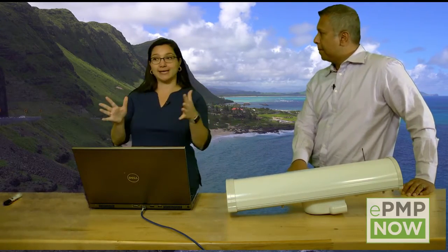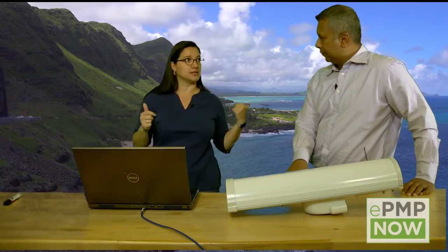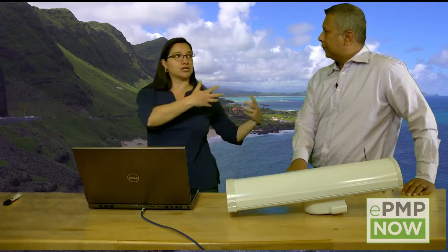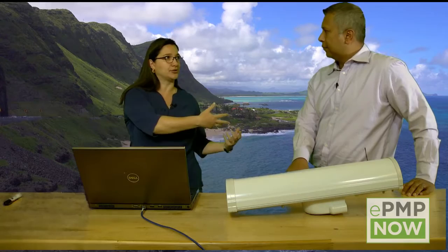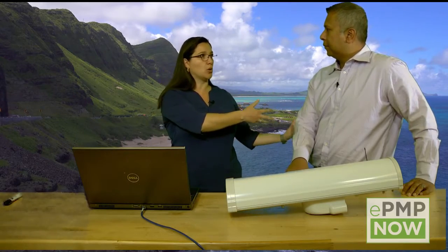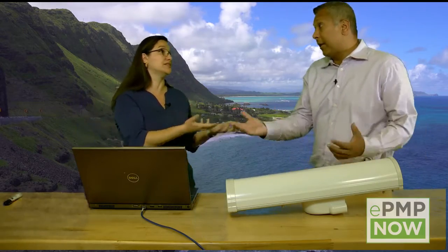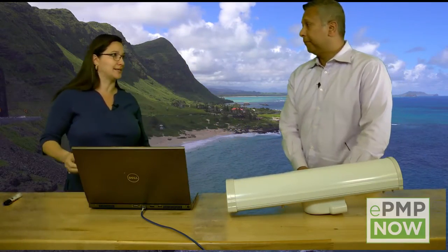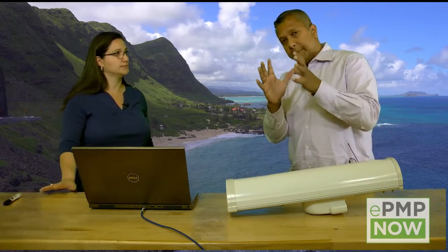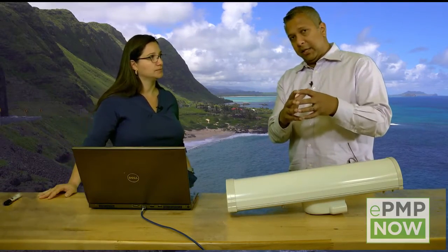Now, in that case, if I'm facing this way, you're facing this way, and I have a lot of energy leaking in the back of my sector, then your subscribers will also hear my signal because they're on the same frequency. Exactly. So for the audience, we're talking specifically about front to back, but I think there's a lesson here in terms of the concept of frequency reuse.